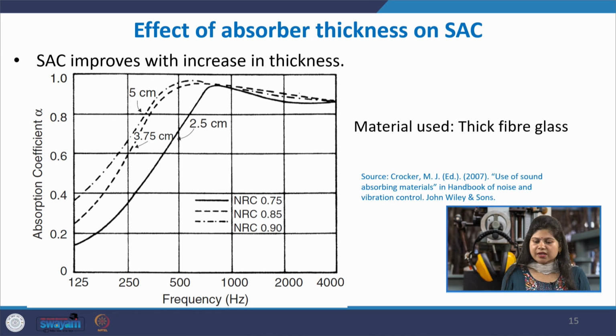So here you can see with the same logic, as you increase the thickness, the SSE goes up, because you are increasing the pathway of resistance, and as they pass through the material, their energy is getting lost continuously. The more material they have to pass through, the more energy gets dissipated till it reaches some optimum level, beyond which the thickness will not have that much effect.